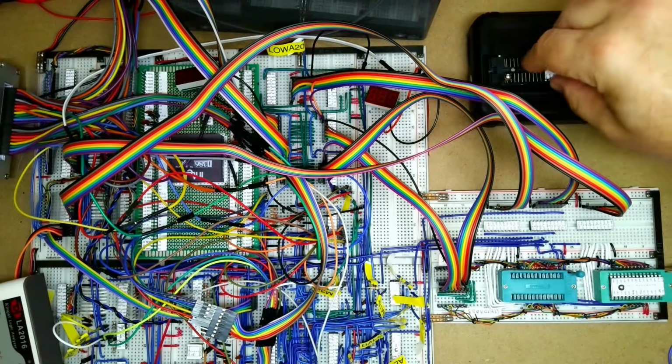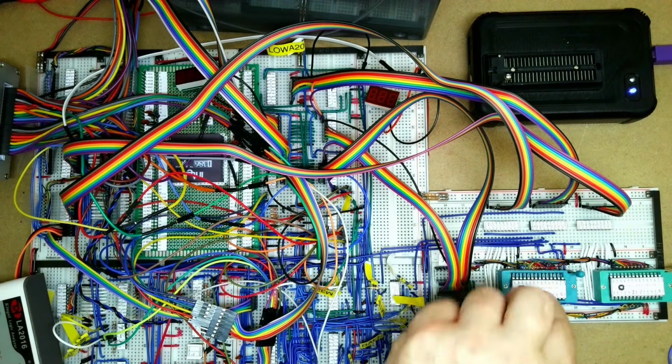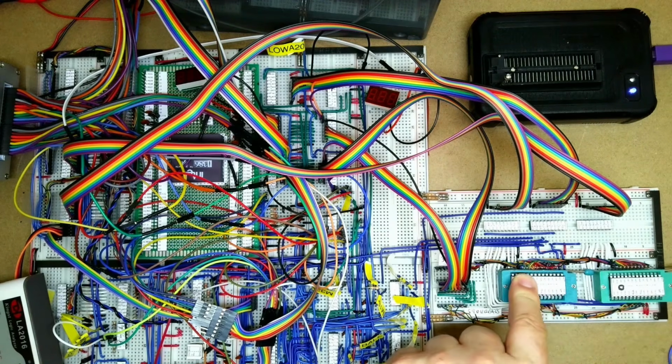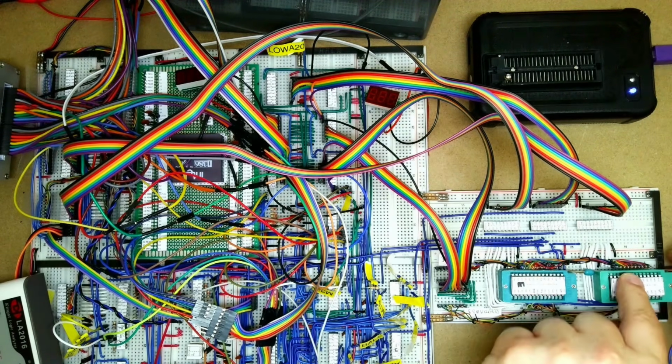When we're taking these in and out, we do need to make sure that things are put in the right way round. And generally pin 1 tends to be up where the lever is. We can see that VCC and red is there. So that should be the right way round. Let's do the other one now.